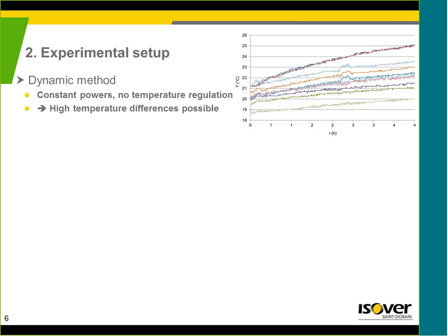This is an example of one of the first steps we actually realized when we started to develop the method. If you don't do it properly, some rooms will be heated by 1-2 degrees when some others will be at 4 or 5 degrees. And if you want to make the hypothesis that your temperature is basically homogeneous in your building, then you can't. And so the averaging that you want to do is problematic and can lead to rather high errors because it's also related to where exactly you put your sensors and everything.